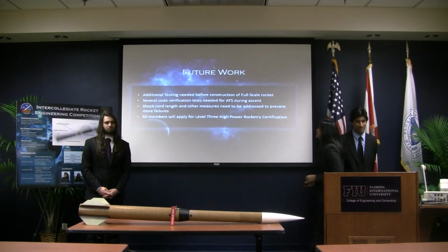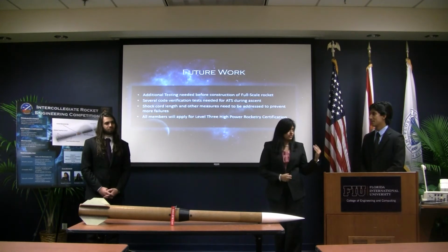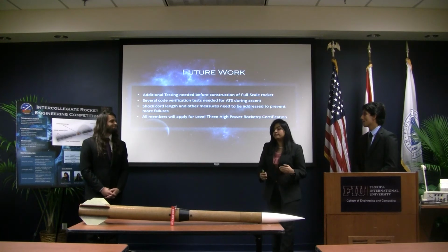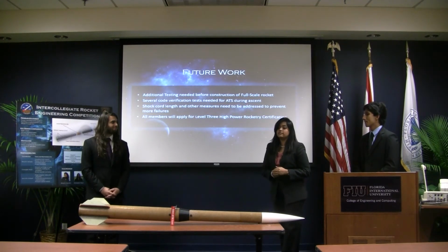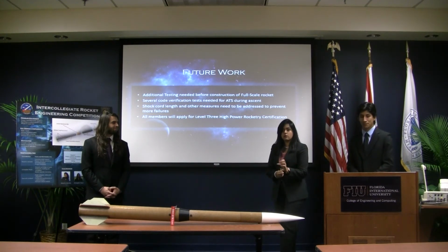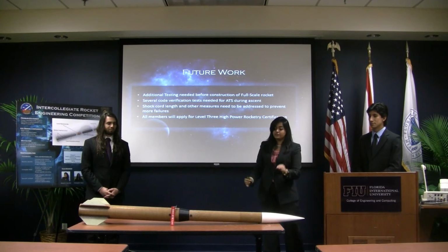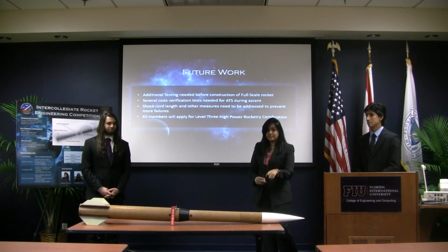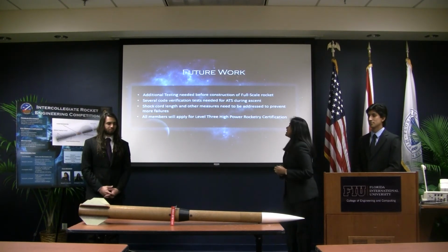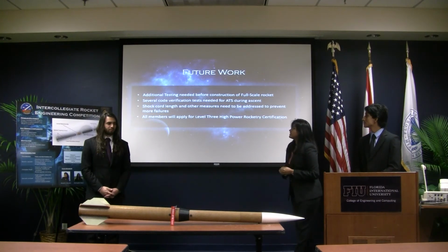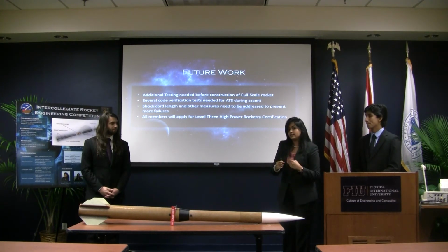Thank you. Now, as far as future work is concerned, and as Giancarlo mentioned, the complete flight of the subscale led us to believe that future testing for certain components of the rocket needs to be performed before putting them into the full-scale flight. The rocket is twice the size of this subscale here. So additional testing, such as the shock cord lengths so that the tangling doesn't happen again.